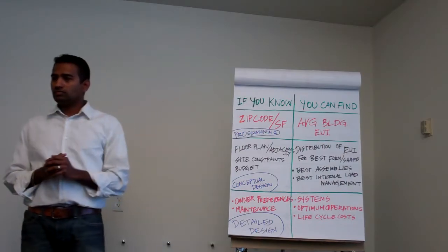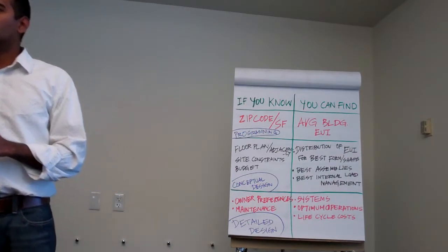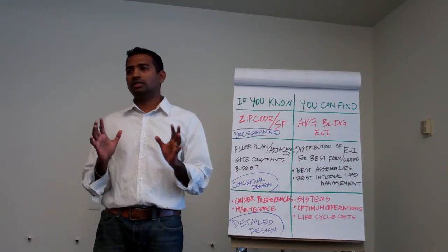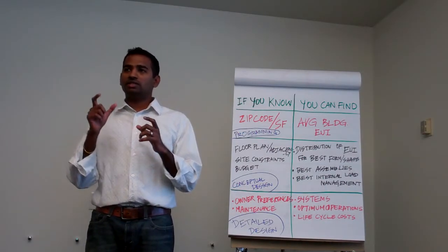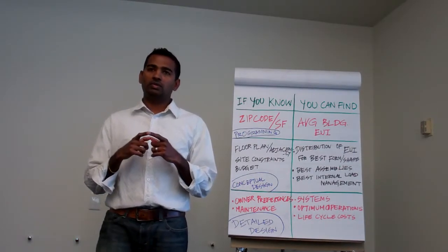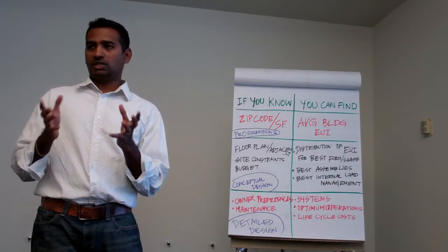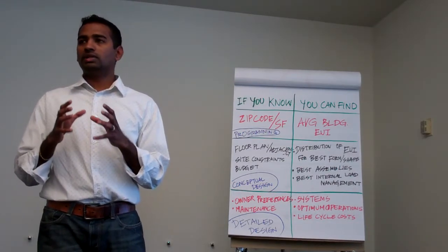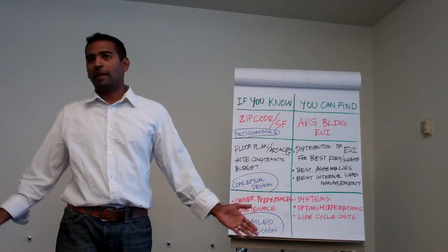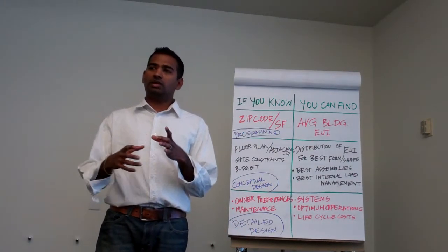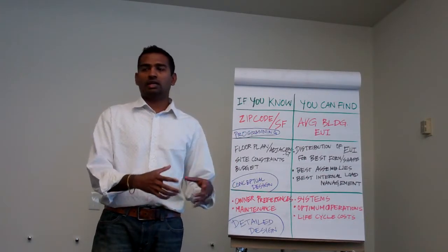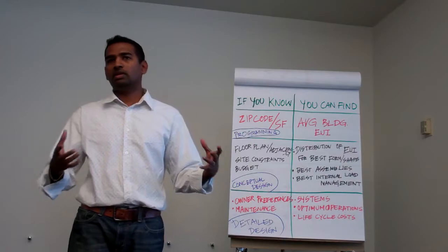Well, some of the stuff on the code plan is actual versus the square footage occupancy. Right, and we can spend a day on discussing that topic. But the gist of it is, our designs have to be designed for worst case, right? Worst case, I could have 150 people in a media center or something. So my mechanical system should be able to handle that 150 people. But theoretically, that could only be 26, 30 people every hour.